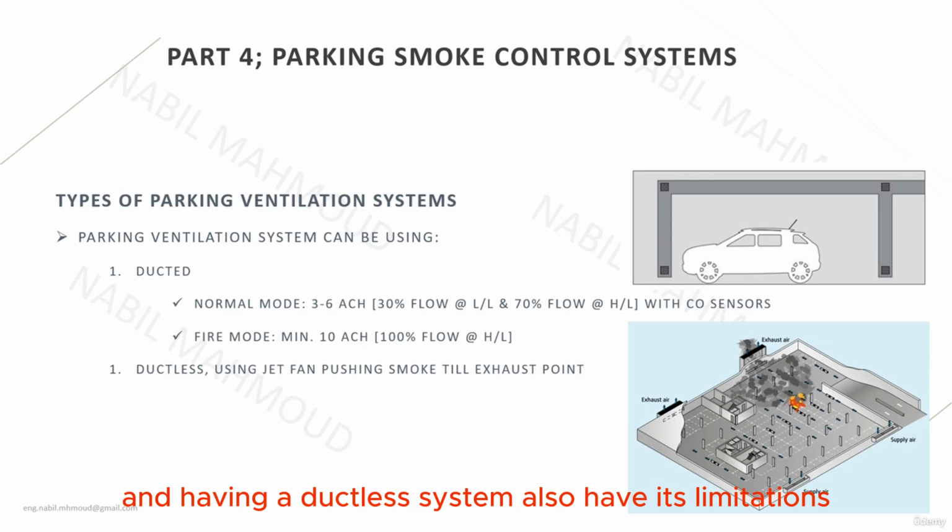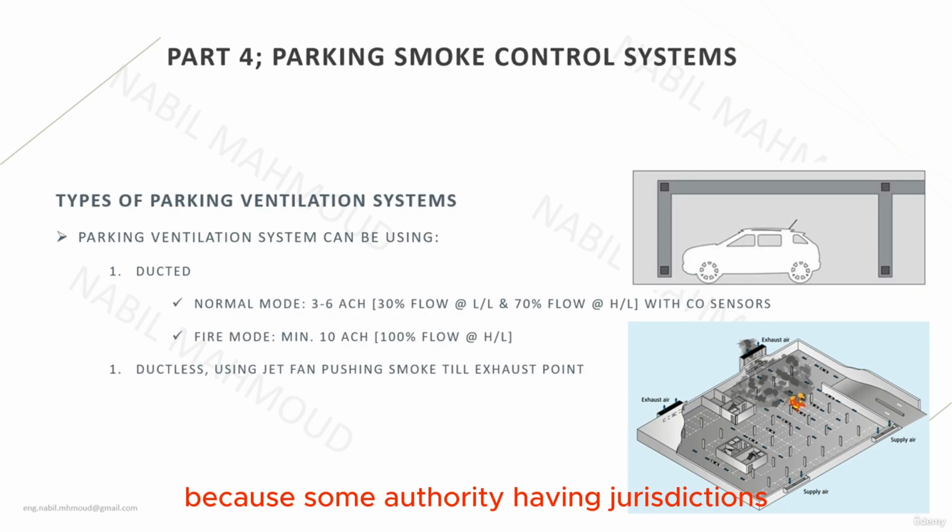And having a ductless system also has its limitations, because some authorities having jurisdiction have certain restrictions or limitations on the application of jet fans, and some of them prohibit the usage of jet fans. That's why it is very important to cross-check with the local civil defense requirements and regulations.